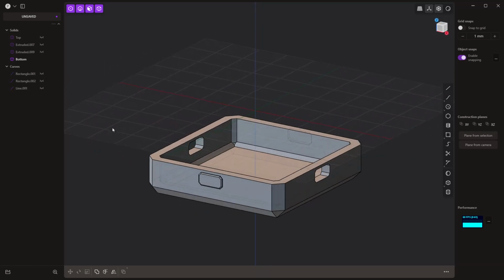matched opening. Now remember the values I talked about initially. 0.1 millimeters, at least on my printer, is a fairly tight fit. 0.5 millimeter difference is going to be a much looser fit. For something like this, we want to be somewhere in the middle, and I'm going to use tapered geometry to kind of take up that extra space. You don't want it to be a perfect fit. You probably don't want 0.1, so somewhere like a quarter, 0.25, that's probably going to be a good value.